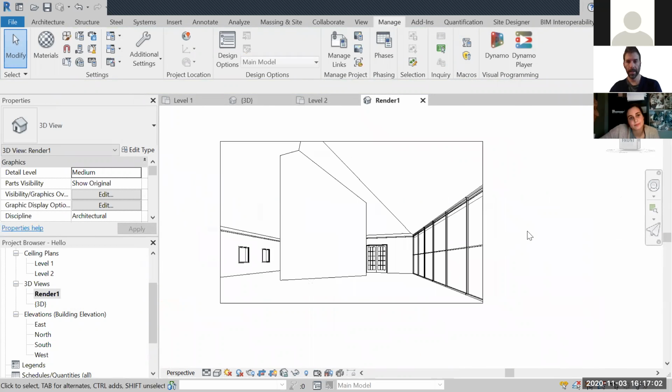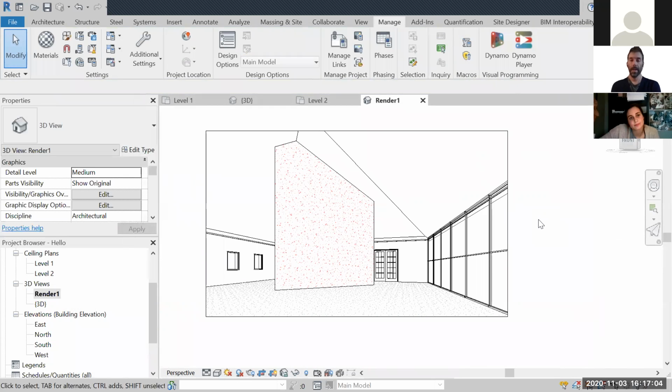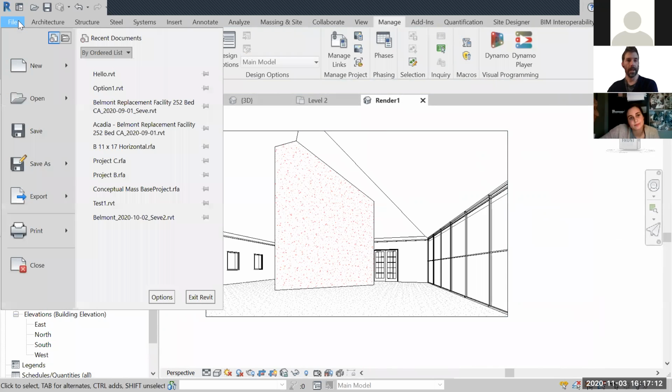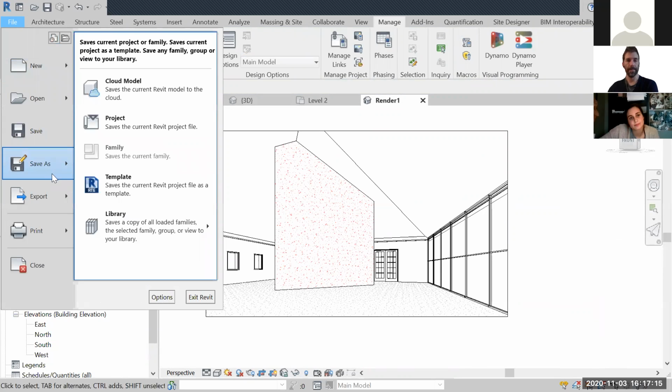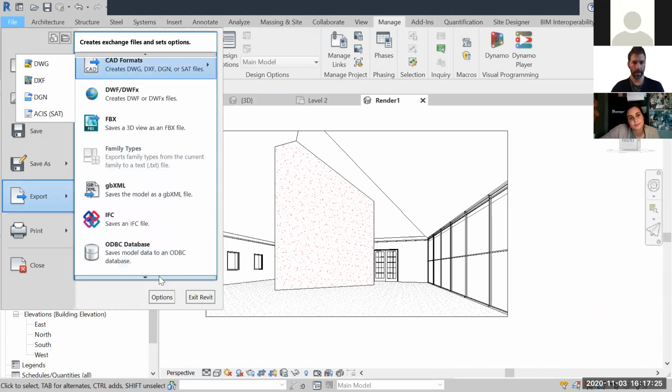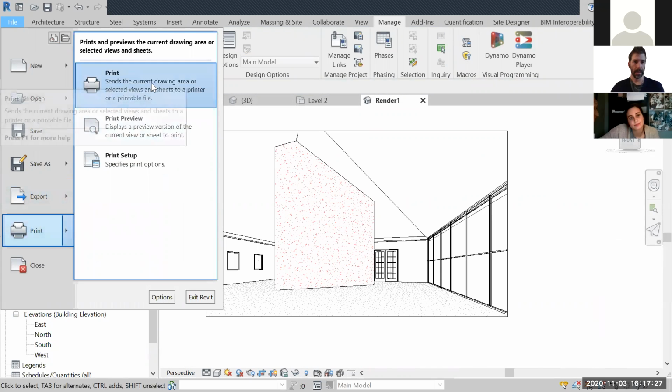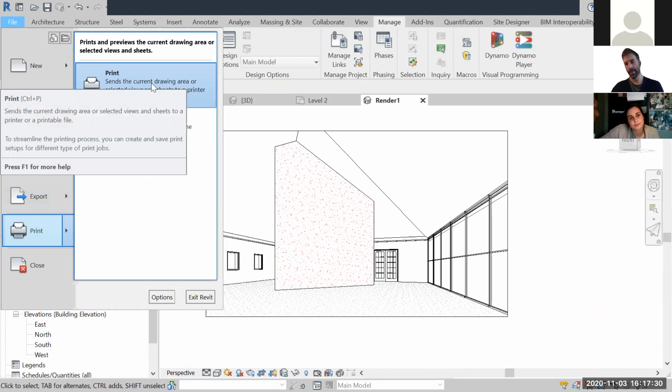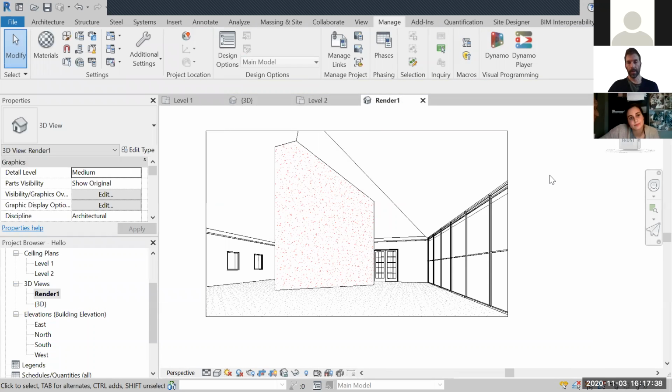That's a red concrete right there. Now again, this is great because many times you want to present your project in a more vector-based quality. So you can export this, as you know, as a DWG, and it will give you all of those lines, and then you can take it to Rhino, etc. But you could also just print as PDF this particular one view, and that will be a vector-based line drawing that you can take to Illustrator as well from the PDF. Okay, so this is great.